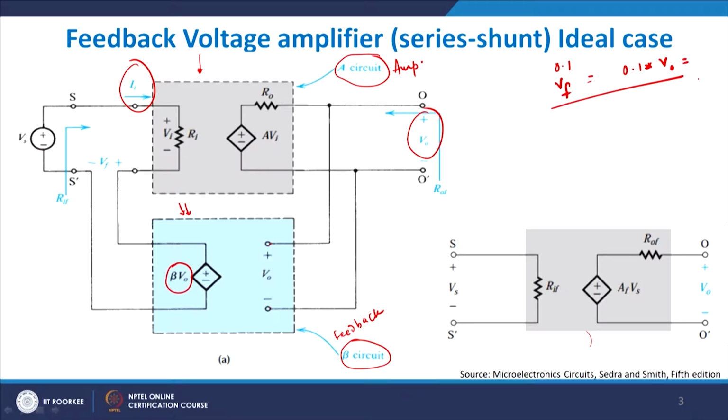This is how we will generate the feedback ratio. Vs is the source voltage, out of which a particular voltage Vi appears here depending on the value of Ri, which is the input resistance of the amplifier. Now, for voltage gain, A equals V0 by Vi, and therefore V0 will be equal to A times Vi, which is what is written here. You will also have an output impedance of the voltage source here, which terminates on the output side, and depending on the value of beta and A0 we will see how it works out.